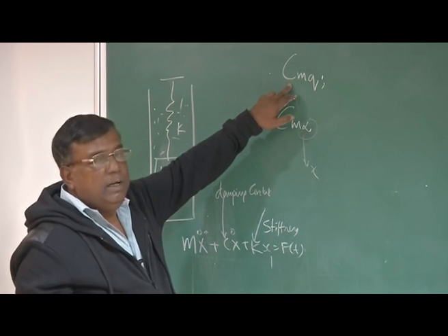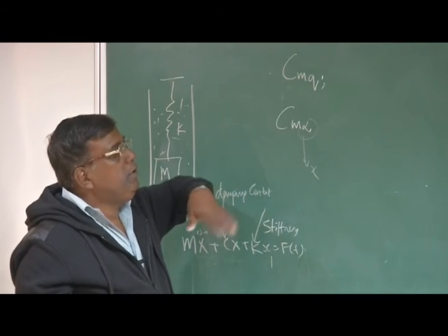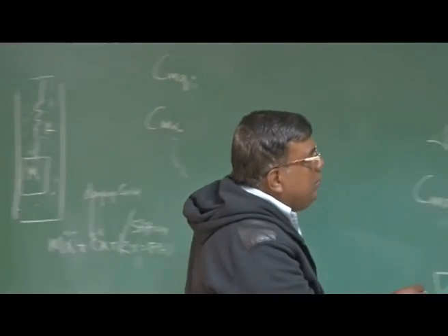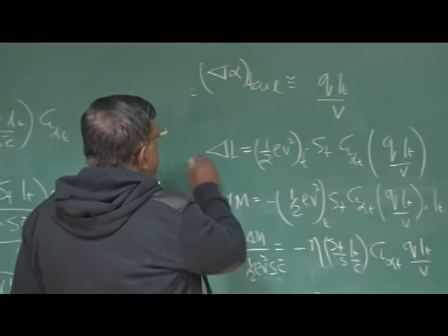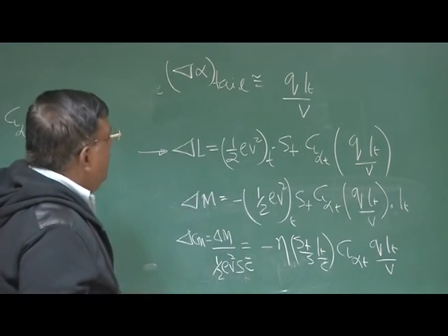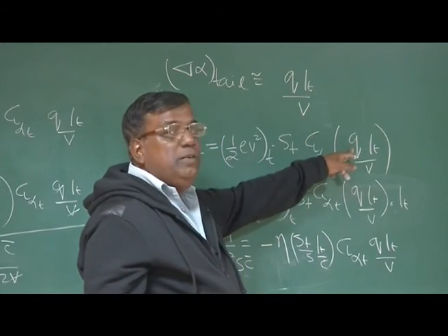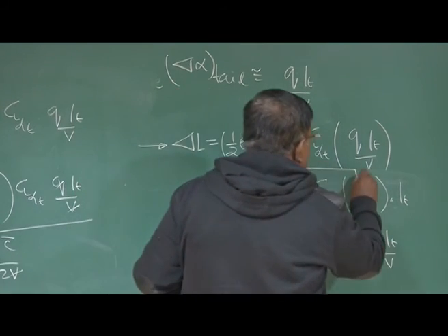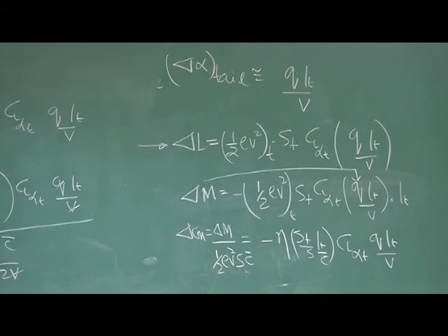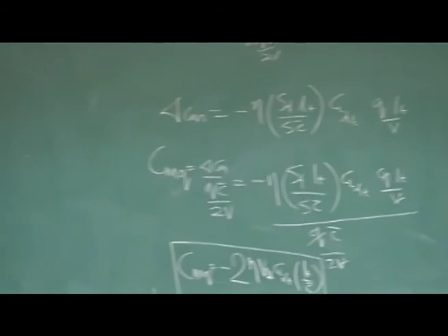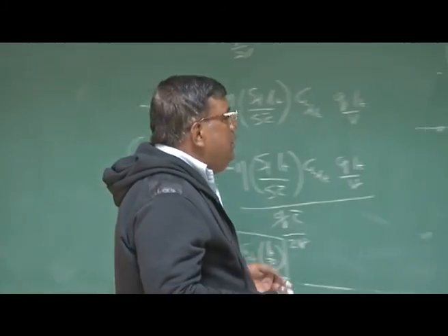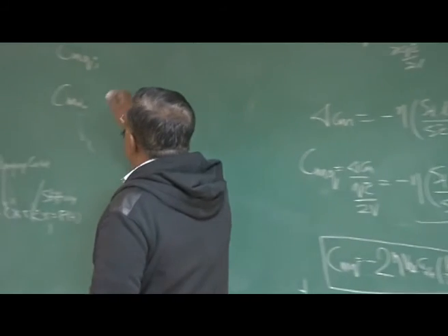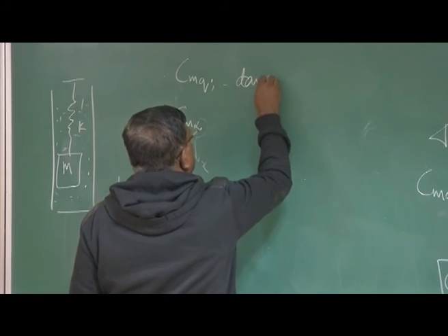So this moment, whatever delta Cm is coming because of q, it is proportional to q. You could see what is happening here, how this moment was generated. There is a delta L, and delta L has a q here. If q is there, delta L is there. Delta M is also coming because of q. So if q is positive, delta M is negative. So this restoring moment is proportional to q, to the rate. That is how we call C_mq the damping derivative.